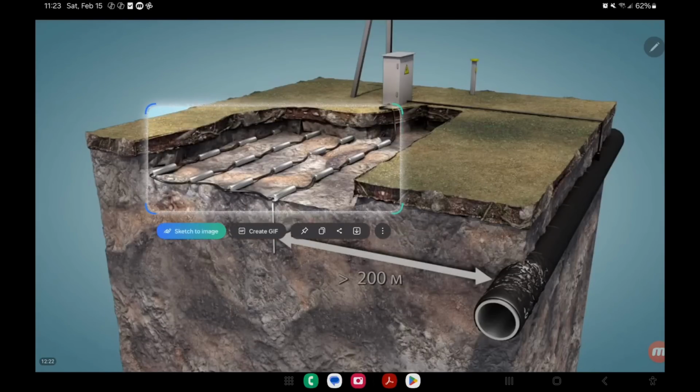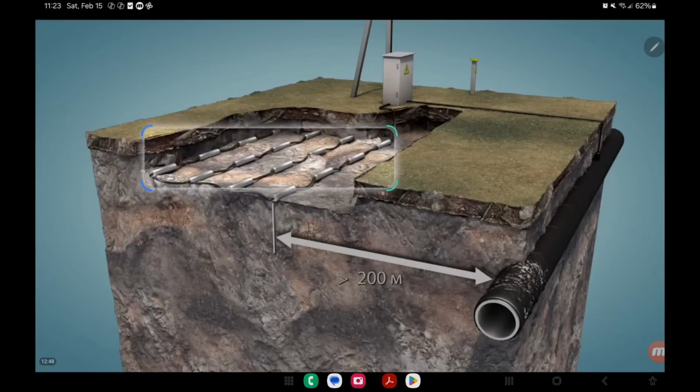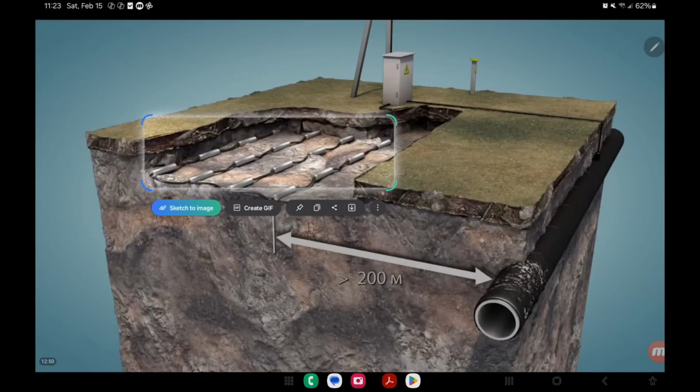But if you want to see it, gentlemen, that total resistance calculation is made up of mutual resistance calculations. Those mutual resistance calculations consider the separation of the anodes and the distance, this separation here. We also take into consideration the separation of one line against another, and the distribution or configuration of the entire system also enters into the mathematical equation.